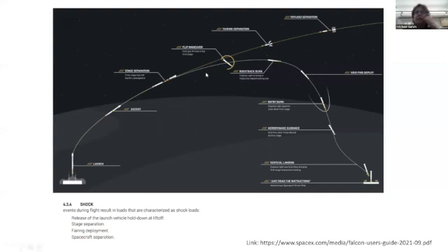A lot of these operations are still performed explosively, and so you can get pretty high shock loads. And then there's just a lot of energy stored in clamping the stages together or clamping the nose cone halves together, and all that energy gets released instantaneously when you separate the stage or you pop off the nose cone. And so those are high shock events, and that shock can travel all the way through the nose cone or all the way through the upper stage up to your payload in the nose cone.